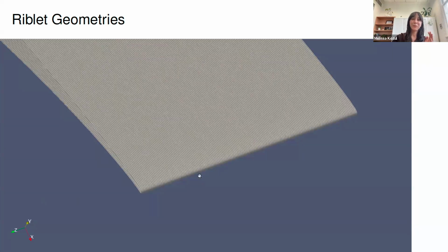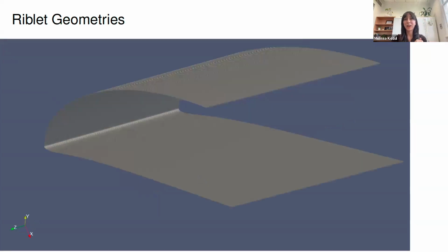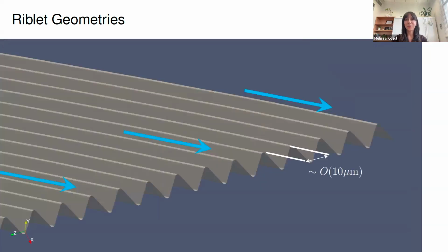So if you count really fast, you have 160 riblets across here. And if I cut through, again, we can't really see them. This is looking at the front of that blade. It's very tiny riblets. And if I zoom in on another cut through, we're on the order of tens of microns here, practically, and the flow is running over the top of those riblets.